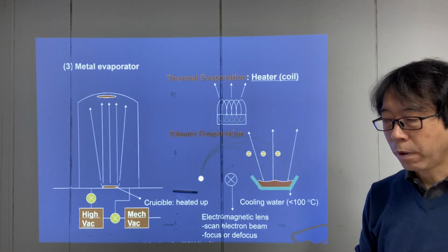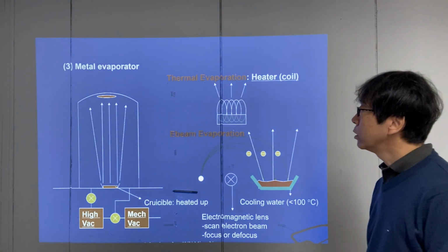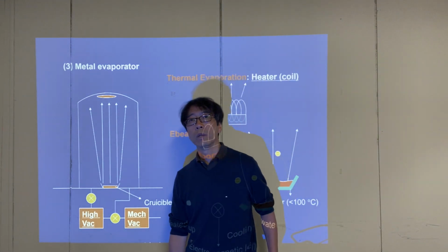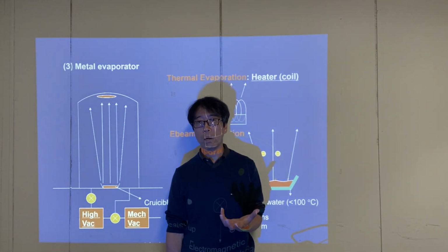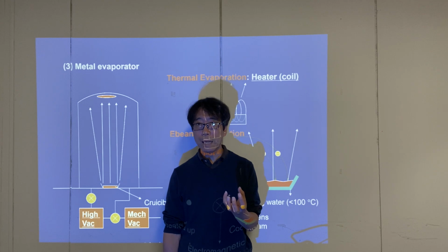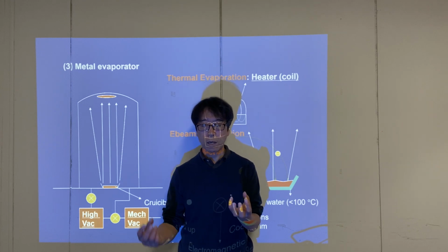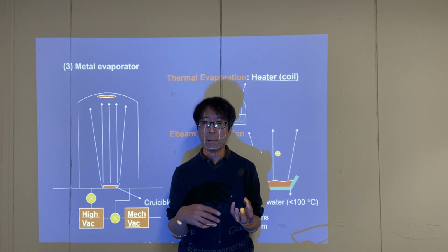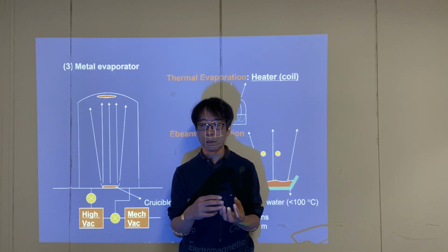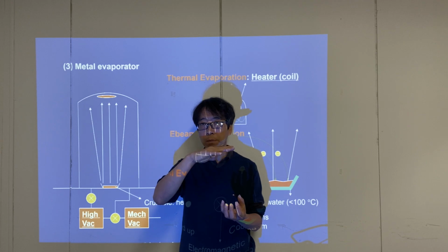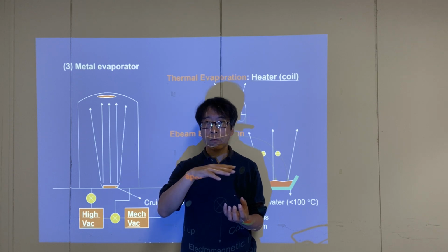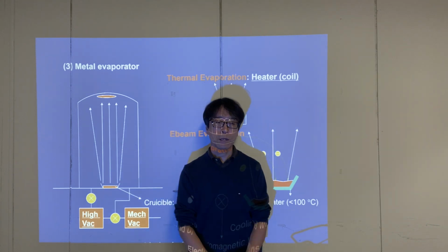Well, the way you deposit this metal is called evaporation. You would bombard the metal pellets with high energy ions, basically currents, and make this metal go up to high temperature, at which temperature is so high, so metal will evaporate, okay?